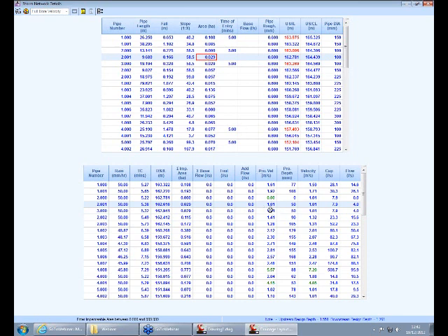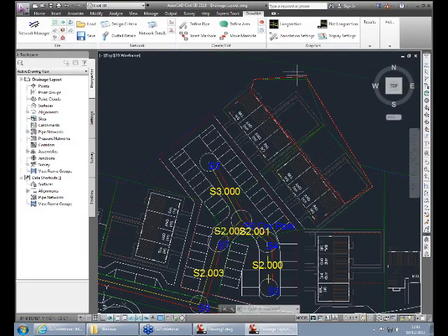We also now see down in our proportional velocities that we're achieving self-cleansing velocities. Not on pipe 2, that's just because we don't actually have any area specified on there at the moment. And I'm not going to spend hours typing in more areas. So I'll show you some other features.